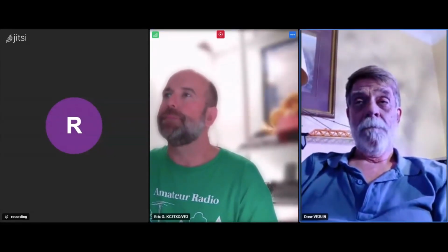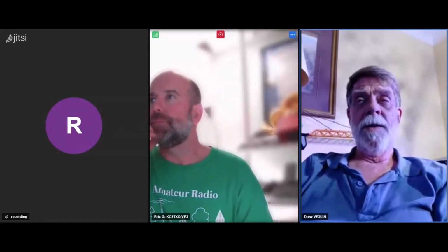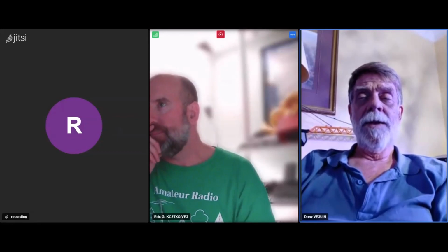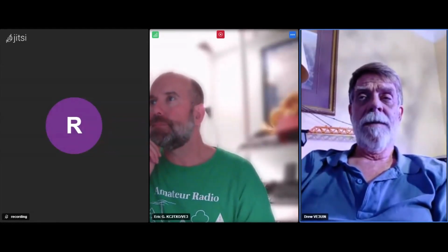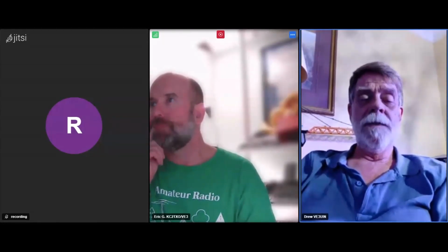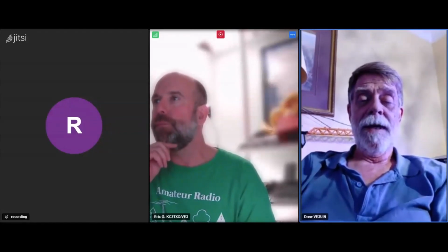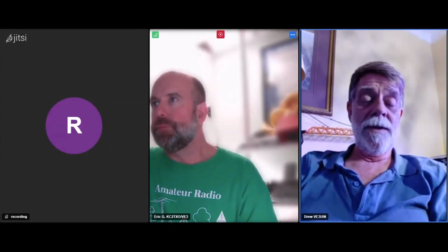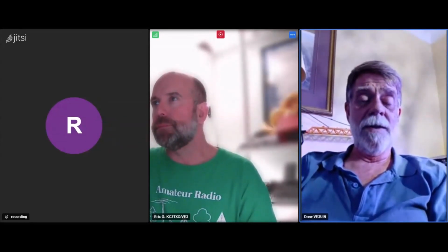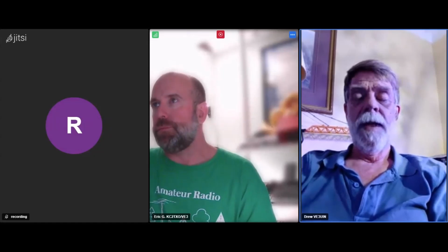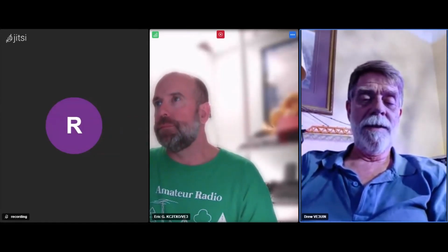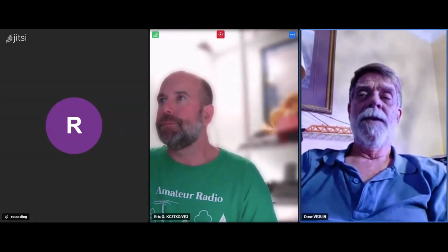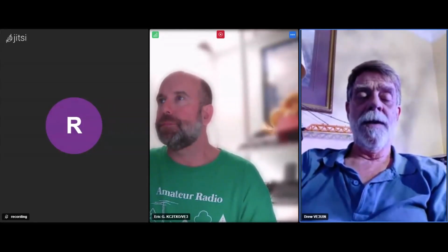Mm-hmm. And the current system that I use, I have an LDG tuner on it, an auto tuner, on an old ICOM. The old ICOM, the max it can put out is 50 watts. It's kind of had its day. So I run that through the LDG and into this terminated end fed, which doesn't require much matching, but every once in a while it needs something, especially when the corrosion starts to get around the eye bolts. Right. And on that, I've hit South Africa and the far end of Australia.